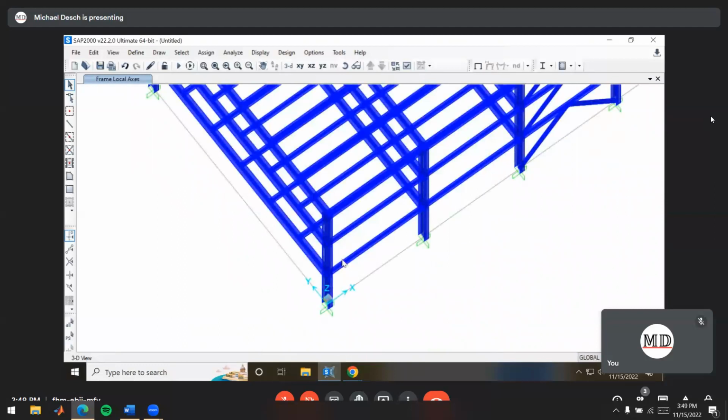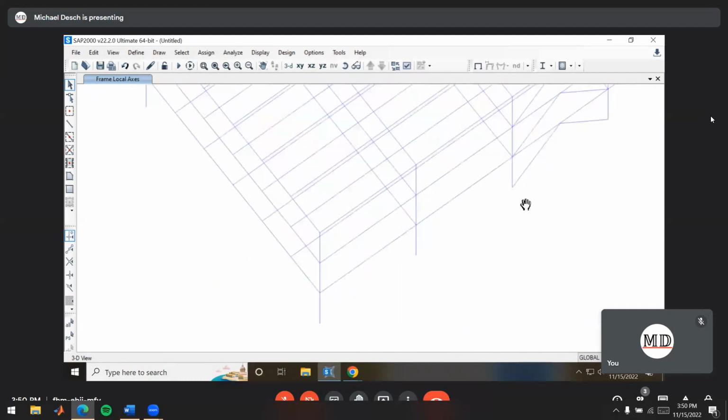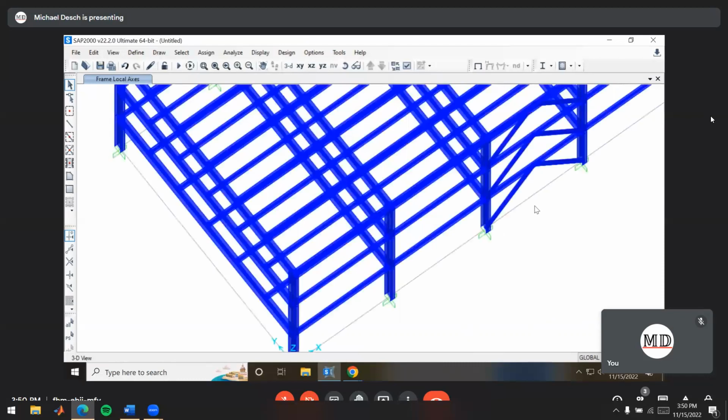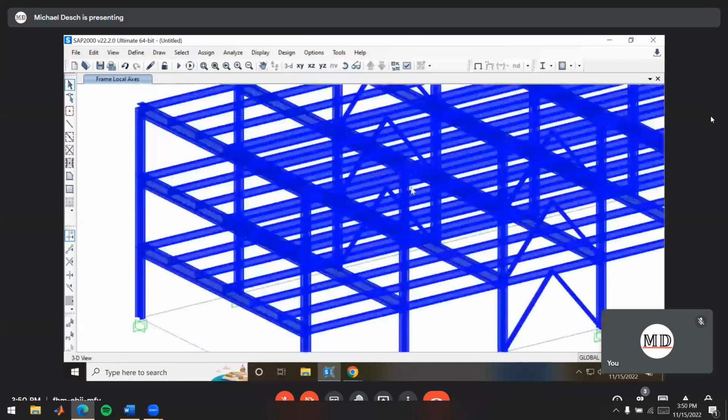Now, we need to make sure we do this, otherwise we're going to be considering the strong axis of the column in the wrong direction, where it's not really being used too much. And we're going to get much worse performance in the moment direction. So we want to utilize the strength of our cross-section in the systems that we can for it. Okay, so any questions on this so far?